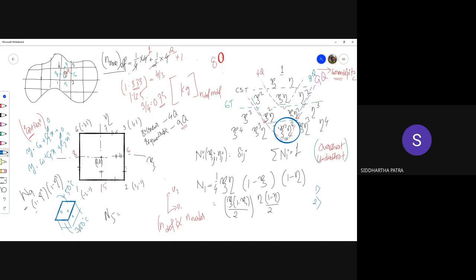The simple solution to that is to go from the quadratic element to simply the linear element. Simply switching to a 4-noded quad element would solve this problem, or for that matter an 8-noded brick element would solve this problem. The problem is that in many of these finite element software, at least in ANSYS I guess, the default option is to go with the serendipity element.